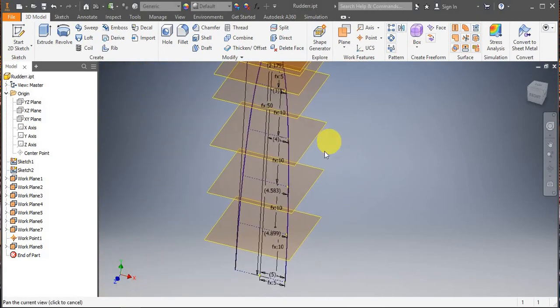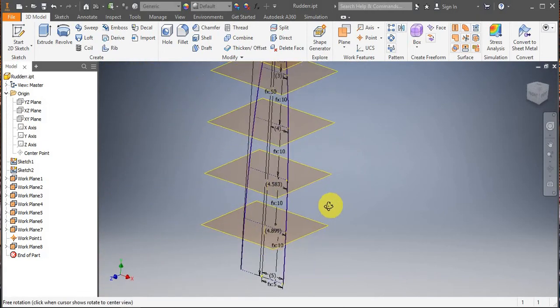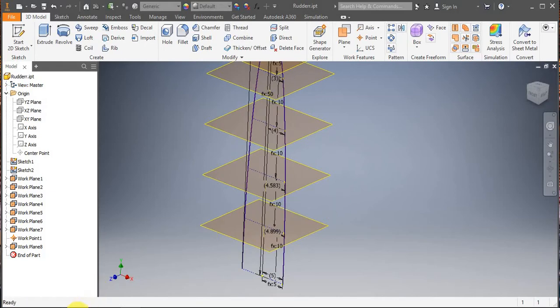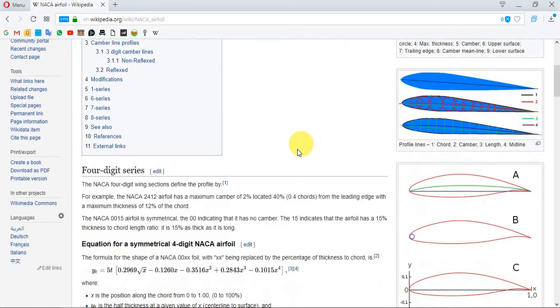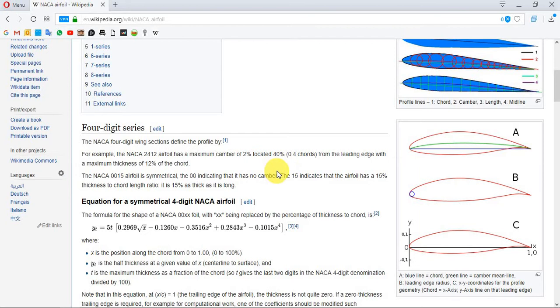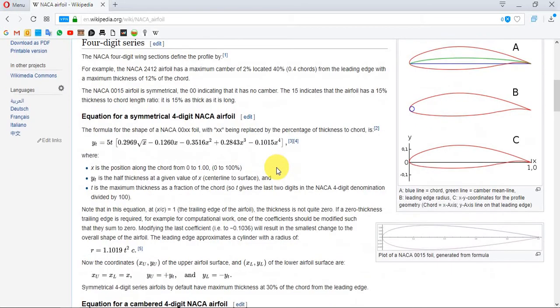So to do that, I will use NACA foils. I don't know if you've heard of them before. They're basically off-the-shelf NACA foil sections. The reason why I would use this is simply because if you try to generate your own foil section, it will be quite hard to estimate what performance in terms of lift and drag you will be getting out of it.